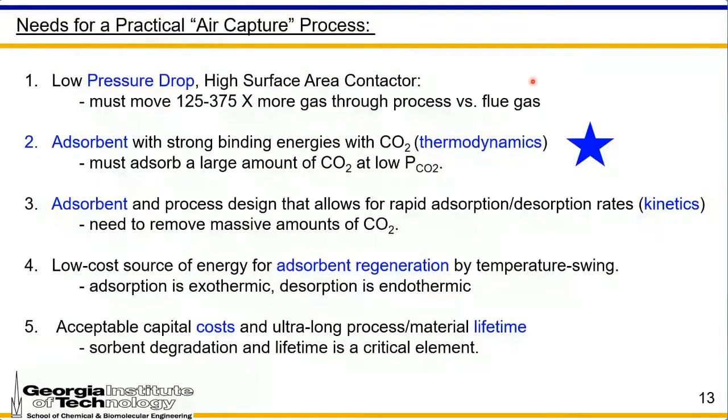And while adsorption is exothermic and happens spontaneously, adsorbent regeneration requires energy input, and so this will be our endothermic step, which will require energy, and we want to minimize that energy that's required. And then finally, we need to have a process and a material that is low cost and long in life, such that we can have overall good process technoeconomics.